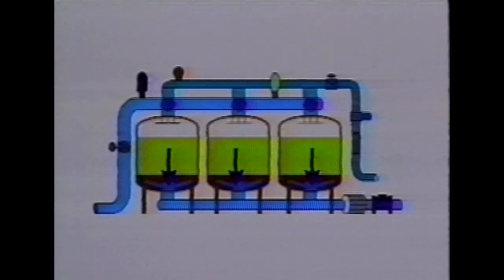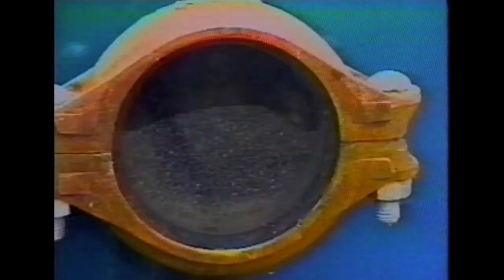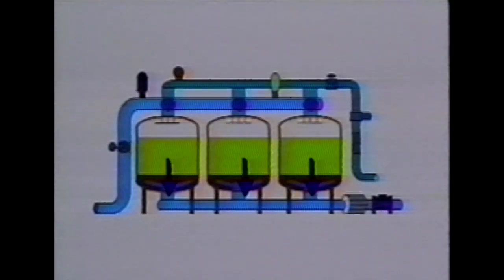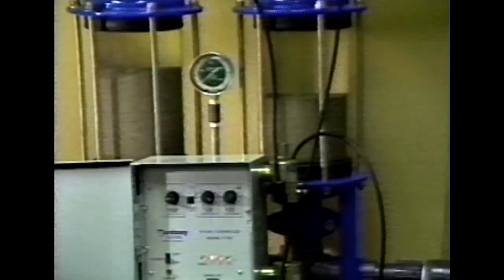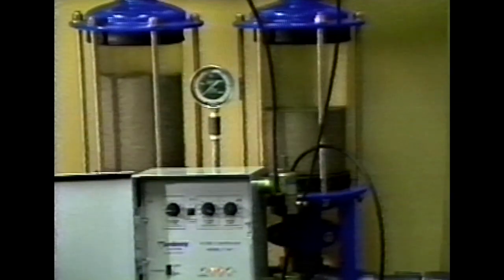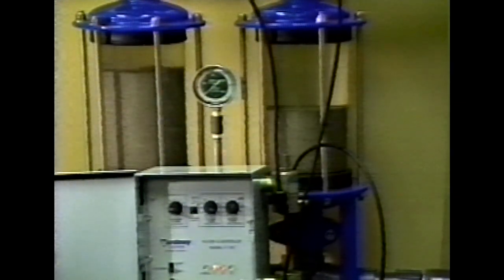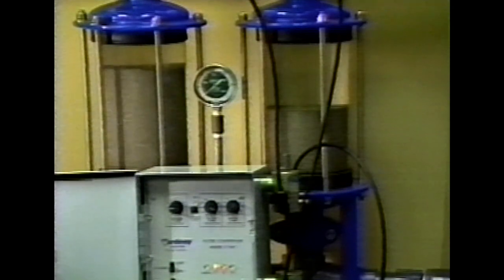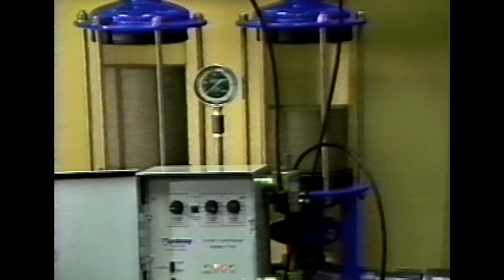Then the water passes through the media, leaving behind the large organic and inorganic materials within the media. After passing through the underdrain to the outlet, the water enters the outlet manifold pipes and then goes to the irrigation system. The backflush process is the most critical part of the operation. Backflush hardware and adjustments are the most crucial aspects of successful media filter operation.